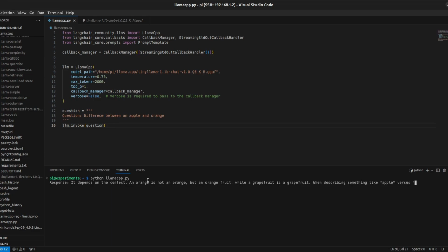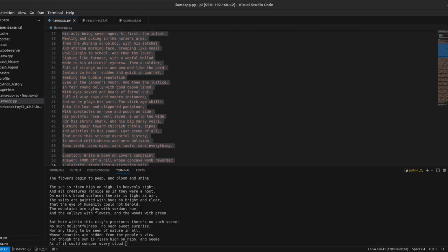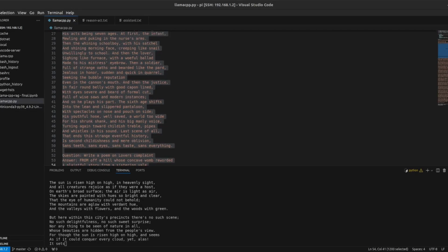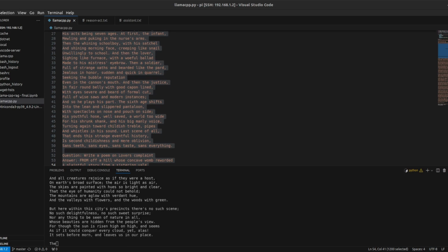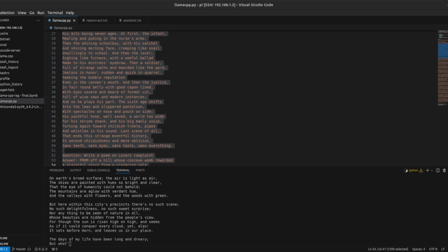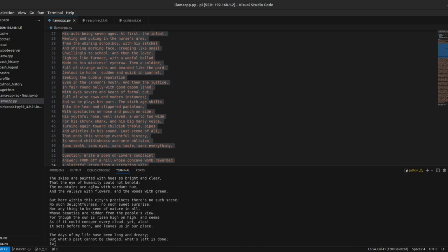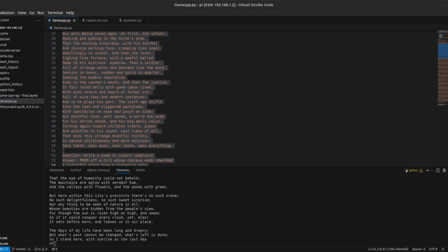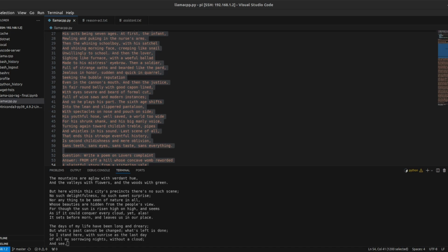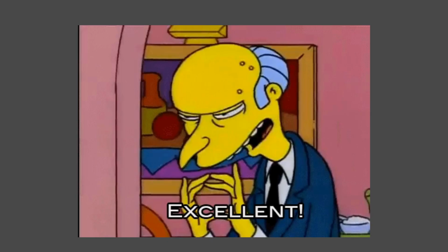Now that you tested TinyLlama on your Raspberry Pi, you can install llama-cpp-python and LangChain before writing a script to develop a poem writer using TinyLlama. Import LangChain and llama.cpp dependencies. Use llama.cpp to load the TinyLlama model from your local path. You can create the prompt for the model to generate the answers. Here, I used 2 poems from Shakespeare as a reference for the model to generate the poems. Once you run the program, it asks you for the title of the poem and starts generating poetic text based on the topic provided. Now, we have a Raspberry Pi with an LLM inside it.